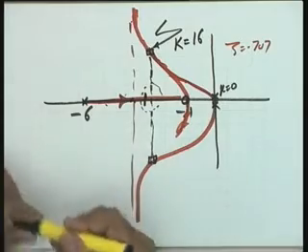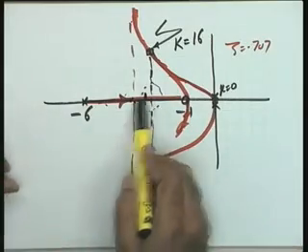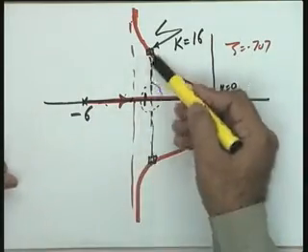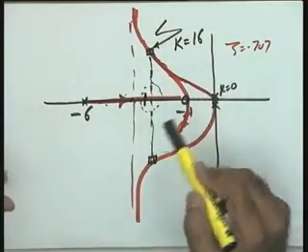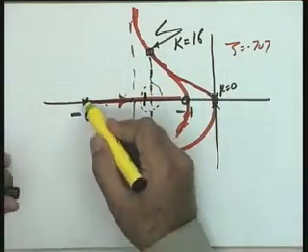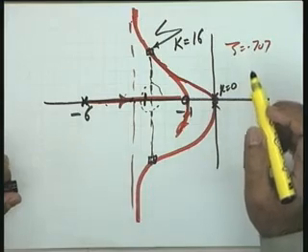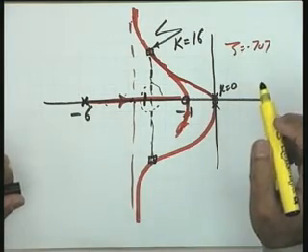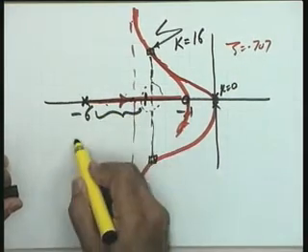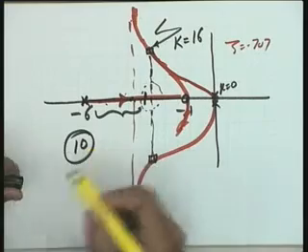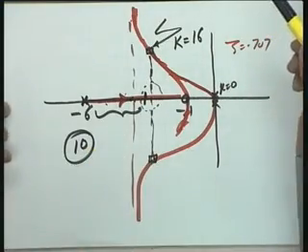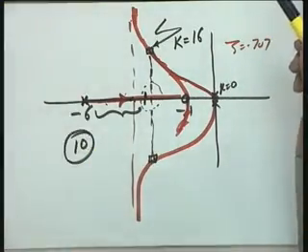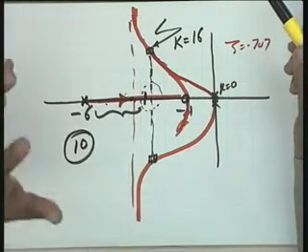One more point, you see, what should be the factor between pole and 0, that of course is guided by this particular thing, but otherwise high frequency attenuation will guide this factor as to how much filtering you require. A factor of the order of 10 normally gives you a better filter design. All these things may be contradictory, but all these things you have to keep in mind.